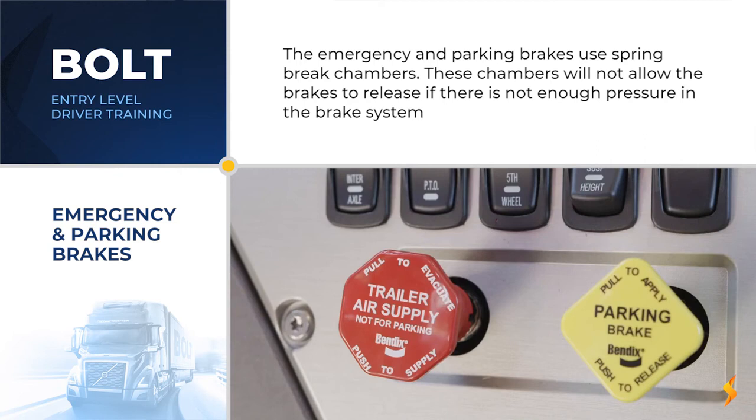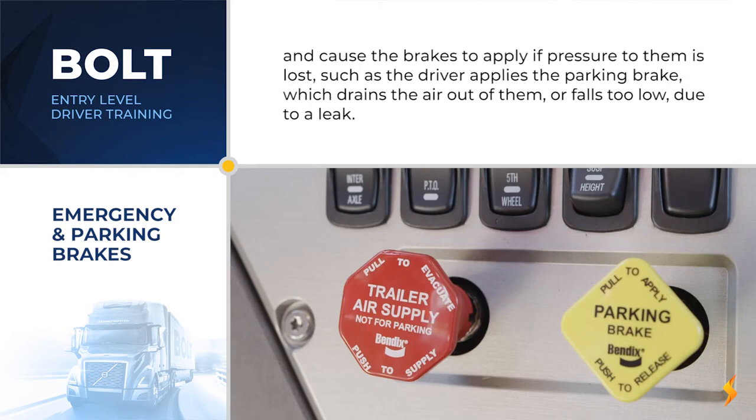The emergency and parking brakes in air brake-equipped vehicles use spring brake chambers. These chambers will not allow the brake to release if there is not enough pressure in the brake system and will cause the brakes to apply if pressure to them is lost, such as when the driver applies the parking brake, which drains the air out of them, or falls too low, such as due to a leak.